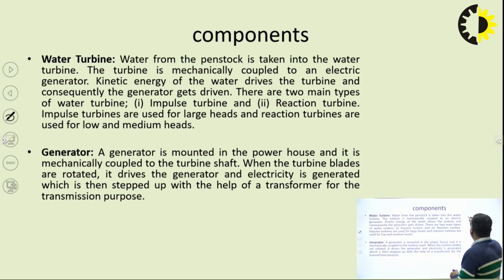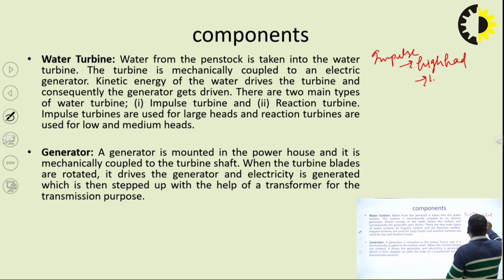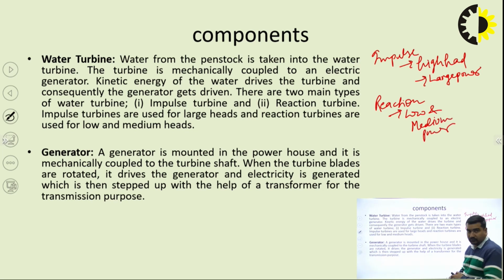So impulse is used for high head, meaning large power, and reaction is used for low and medium power. Okay.